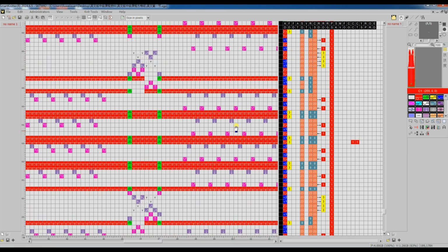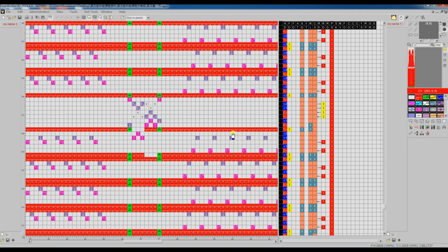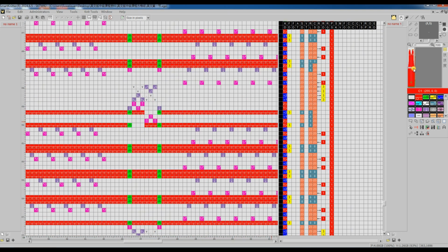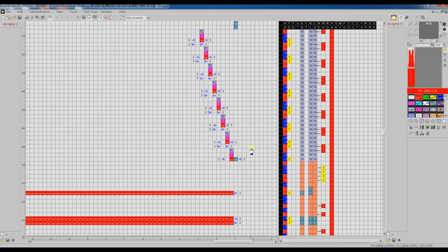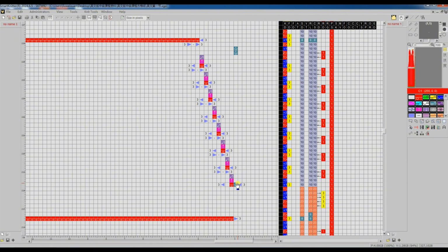The cable and pointelle structures are knitted repeatedly throughout the panel piece. Here we can see the binding off like what we have set up during translation. You can see the stitch hold and press off at the outer edge of the bind off here. 0 courses delay means the stitch hold will be pressed off immediately after bind off is completed.